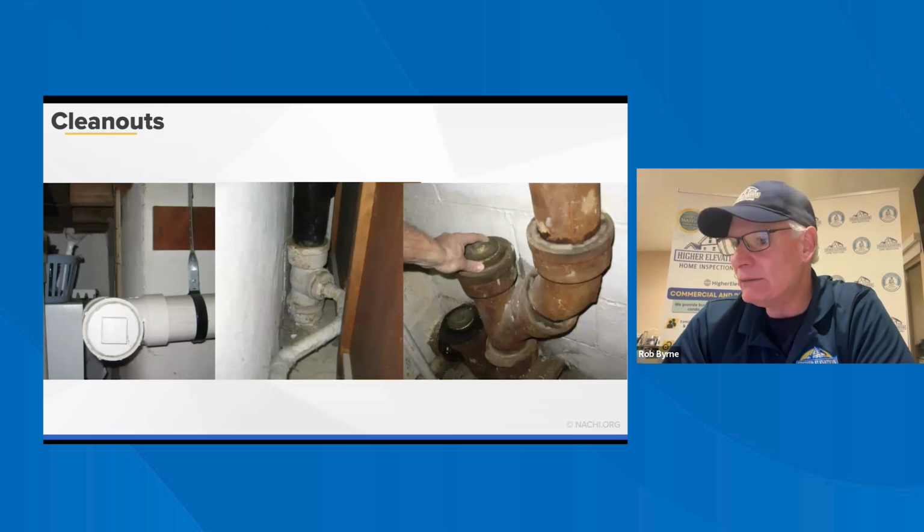It could be a high water table or water coming in. It's not contaminated water. On the other hand, sewer ejector pumps deal with waste. It's dealing with solids. It's grinding it up and pumping it out into the sewer system, whereas the other water that's not contaminated, what we call gray water, you can discharge outside.